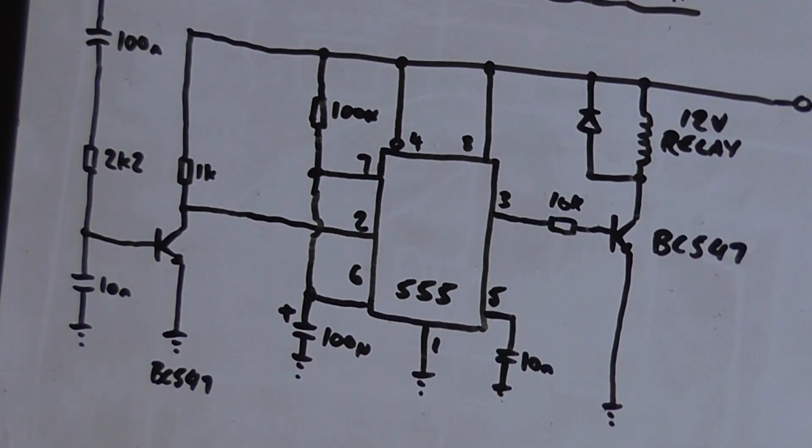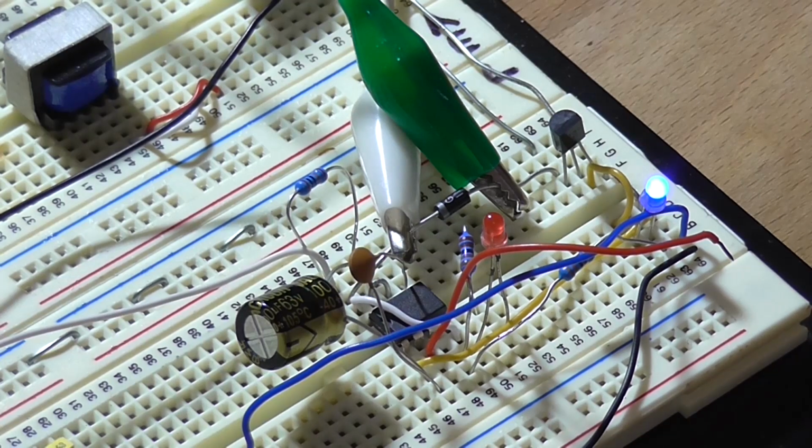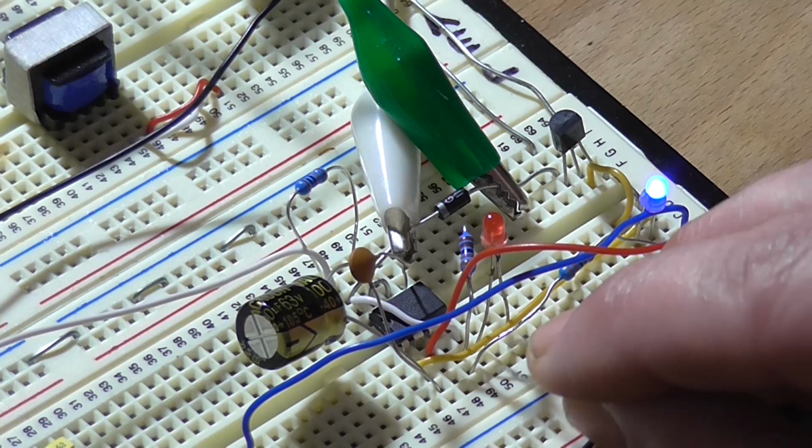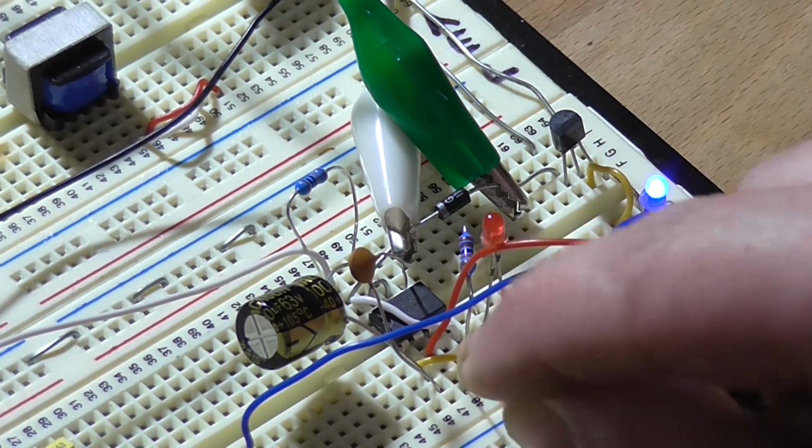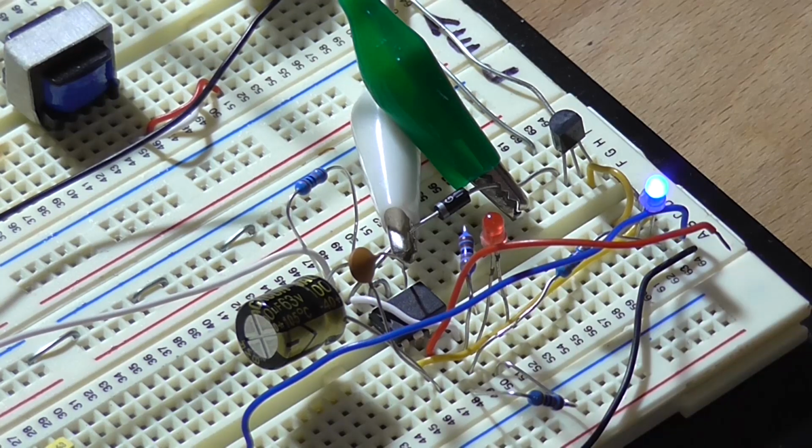I'm actually getting the sneaking suspicion that pin 2 needs to be tied high. So I'll put that 1k resistor in on pin 2 to the positive rail and see if that makes a difference to its output state. So I can probably do this with it turned on. So pin 2 and positive, which is pin 4. Well, not much happened. Oh, there we go. So now it's in the low state.